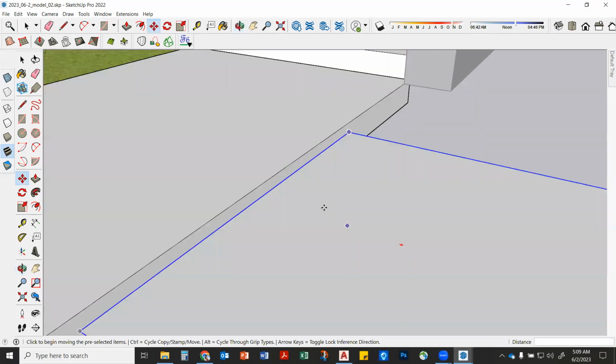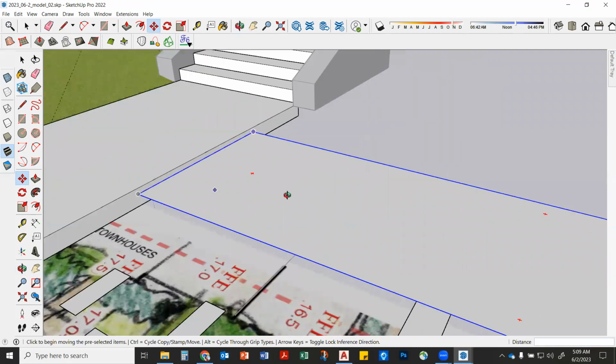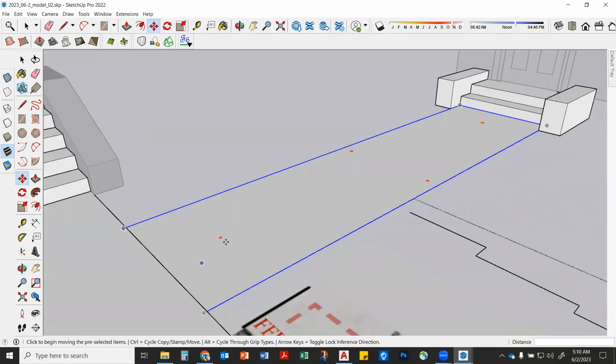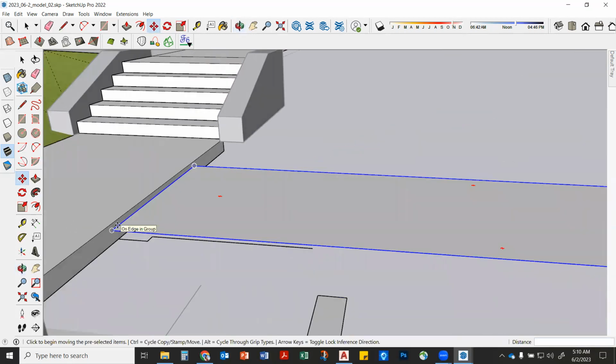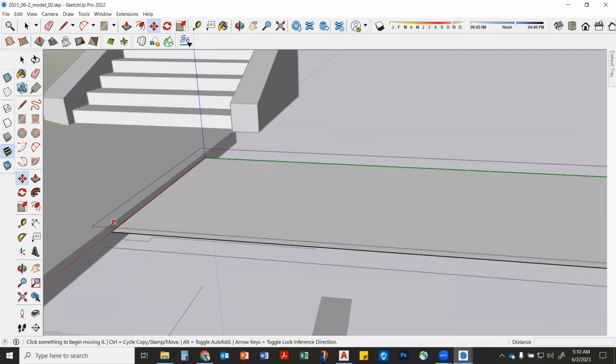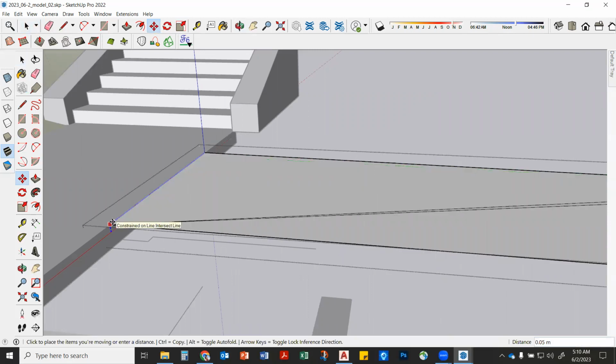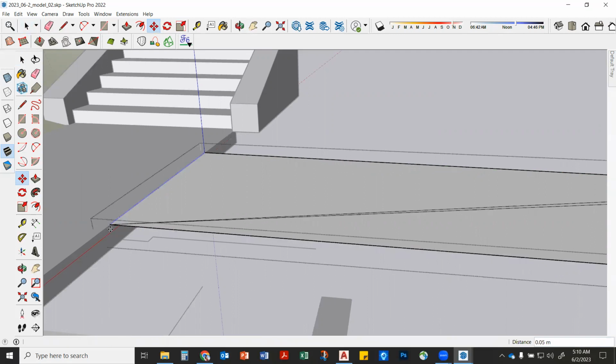Oh, you know why? Because this block doesn't have any slope, does it? This one, in reality, if we were building it, it would. But this one doesn't. So watch, it does have a little bit of slope though, from here down, right? So watch, what do I have to do? All I have to do is select this edge, pull it up with the thread. So watch, I could jump into here, M for move. I could grab that one edge, M for move, lock it up, and I could put it, make sure it's connected right there.